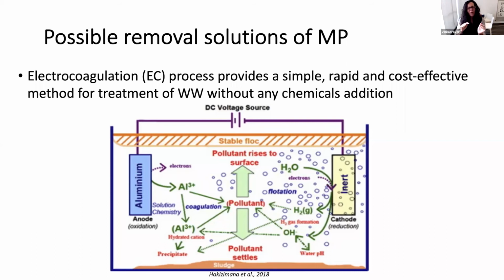On the other side, if we have, for example, an aluminum anode, it's going to be releasing aluminum ions. It happens to be useful because aluminum is a very good flocculant, meaning that it forms some type of network when it's in water. So now we have this network, like a filament, that gets formed because of the speciation of the aluminum. And then we have the bubbles. So we can trap things with this mesh of aluminum, and then the microbubbles are going to be lifting it up. So that's what we wanted to study.